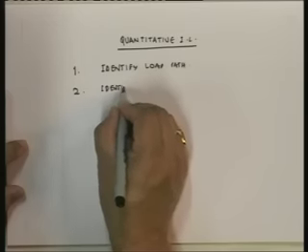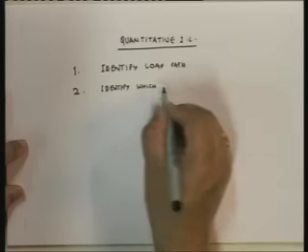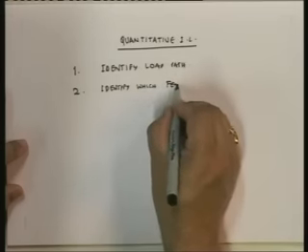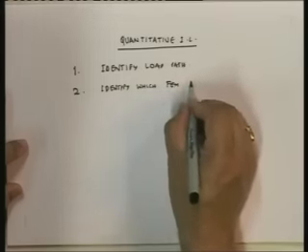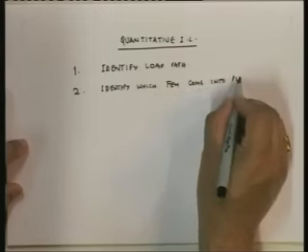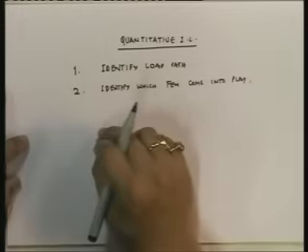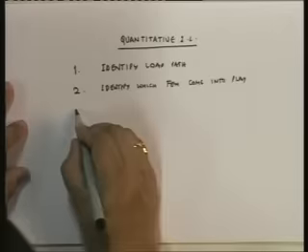Identify which fixed end moments come into play. When you know the load path, you know exactly which fixed end moments are going to be non-zero as the load moves from whichever point to whichever point we want it to move. So identify which come into play.